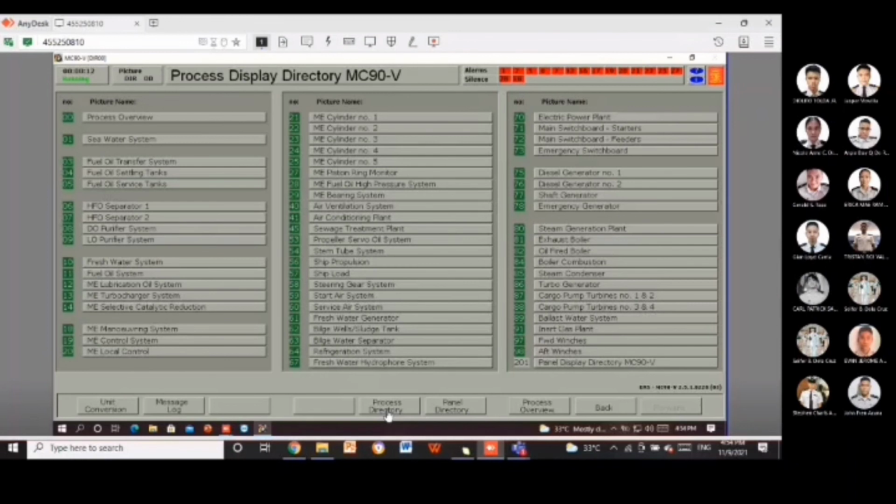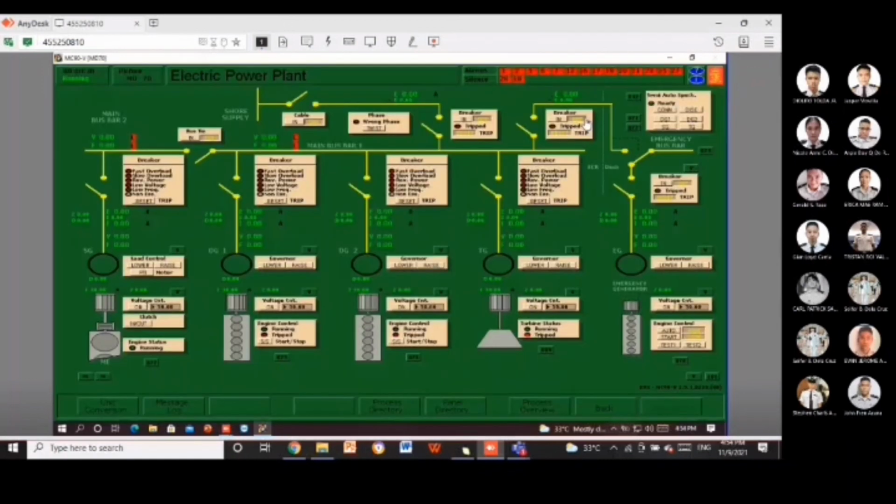So first thing to do is go to MD70 which is the emergency generator. Second step is go to start emergency generator on engine control. Then next is switch on the voltage control, then check the voltage and frequency. So let's proceed to Engineer Antonio for other steps.